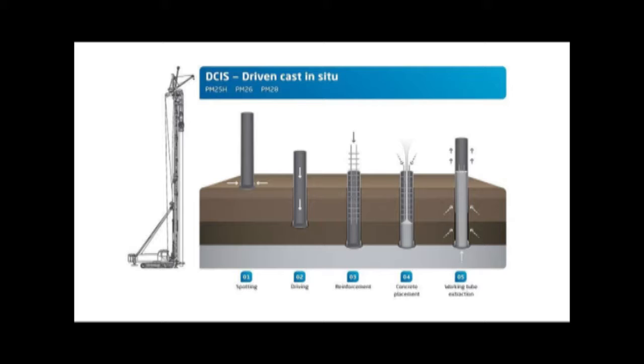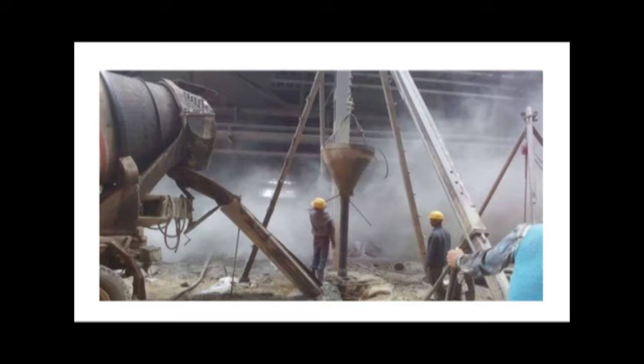Cutoff depth is a depth that is otherwise also to be chiseled off or chipped off or mechanically taken away to reveal the reinforcement for further construction. But why is it taken away, or why is it known as cutoff depth? Because this is the depth where the mud particles are accumulated with the slurry of the cement, or the slurry gets piled up at the upper surface, or it's mostly the cement slurry covering the area. So that is to be taken away, so that the reinforcement may be revealed.